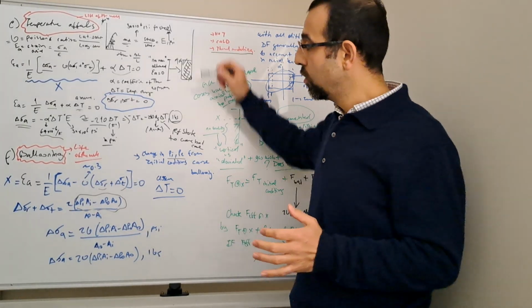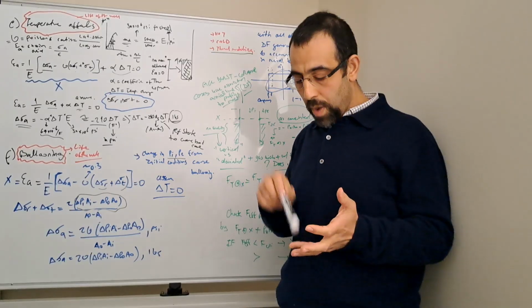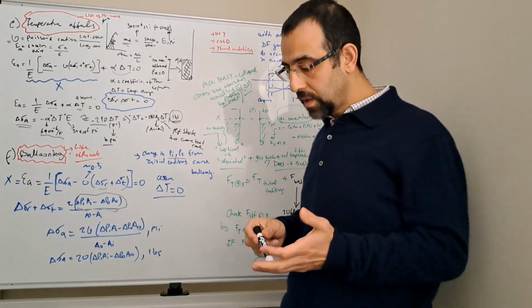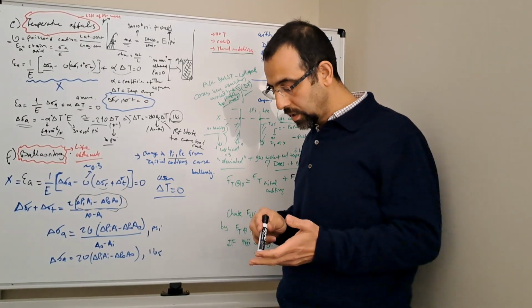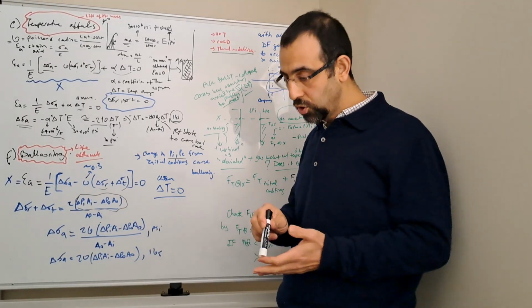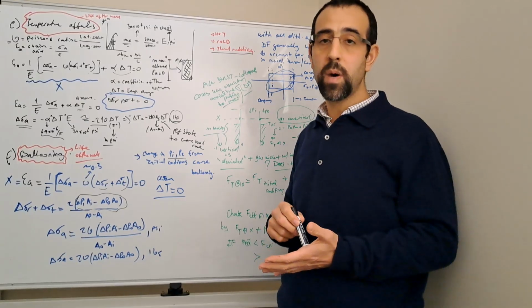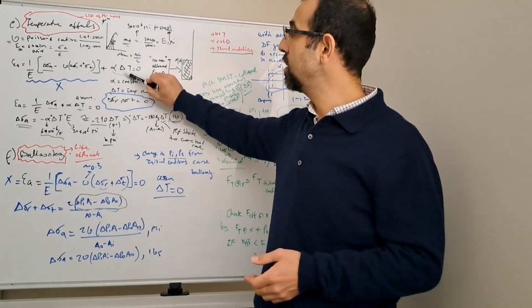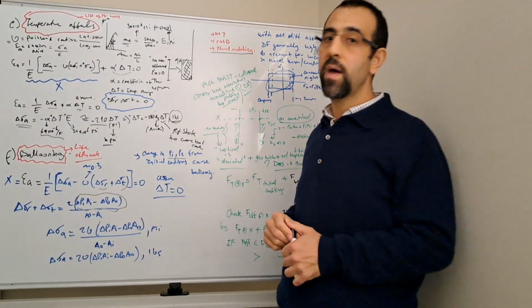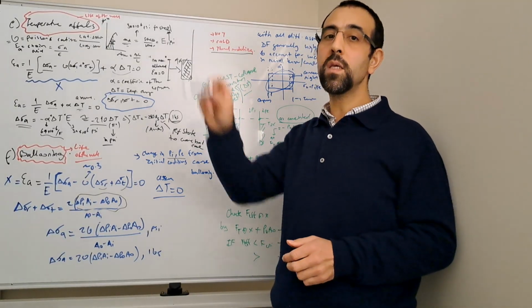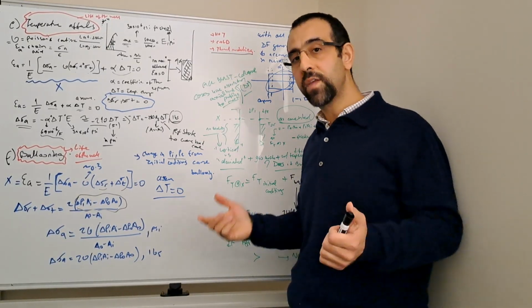It is because you have all these things: the ballooning related tension change, temperature related tension change, bending, shock loss and friction. Yes, we could estimate this, but for example, for the temperature change, we don't have a very exact measurement at each part of the casing, right? We do a thermal modeling.